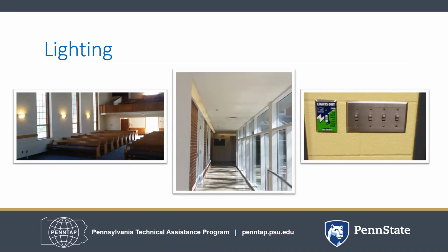IES recommends 20 to 50 foot-candles for office spaces, 30 to 50 foot-candles for gymnasiums, 10 to 30 foot-candles for loading docks, and 20 to 50 foot-candles for mechanical rooms.